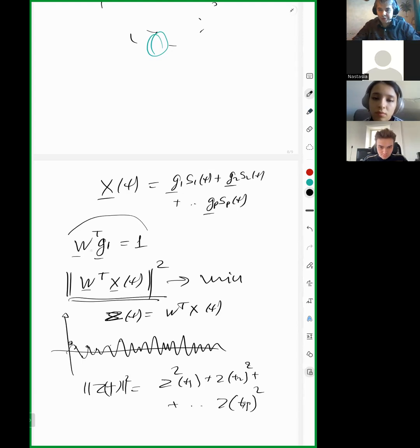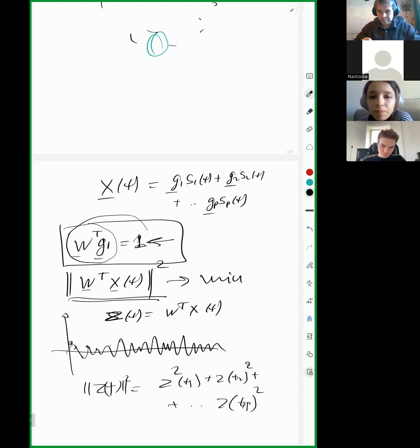Unless you put a constraint, the solution W is 0, right? Here is your minimization of the power. Well, what's the problem? 0, that's it. Well, you say, no, this is not going to work. I want to listen to someone. Here is the guy I want to listen to, G1, a property of this guy. So make sure that the gain for this guy is 1, and after that, just minimize this power, but with the constraint that W transpose G1 is 1.